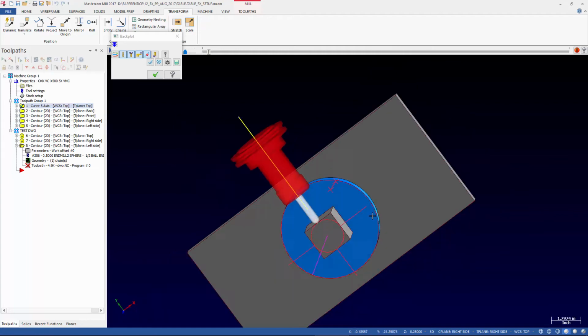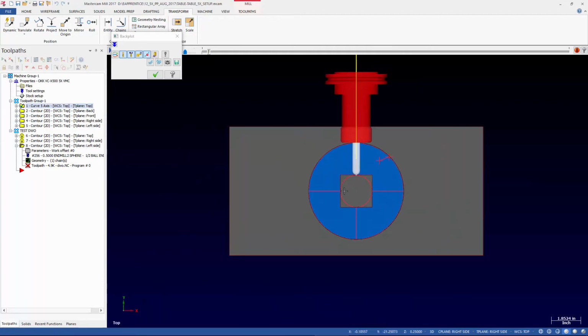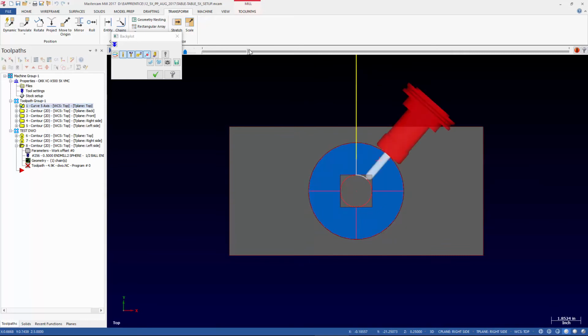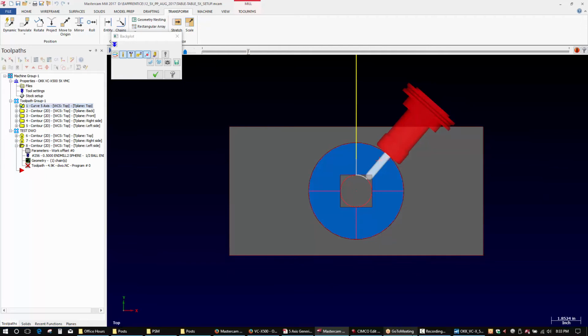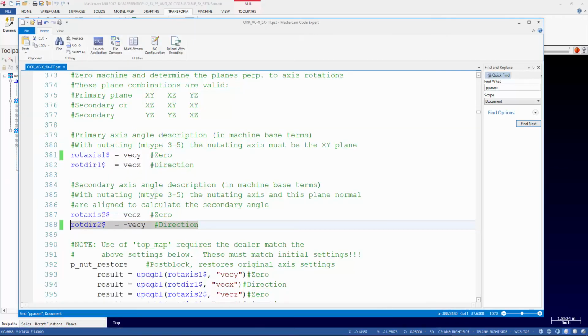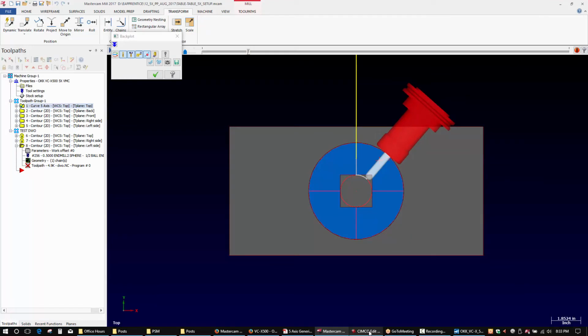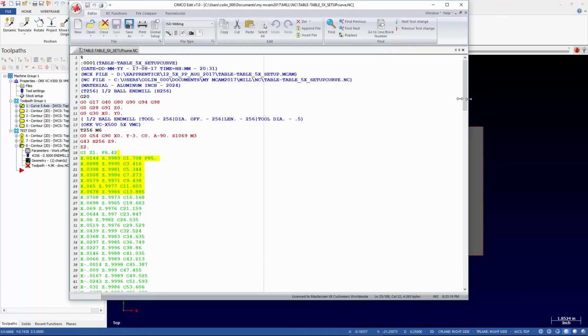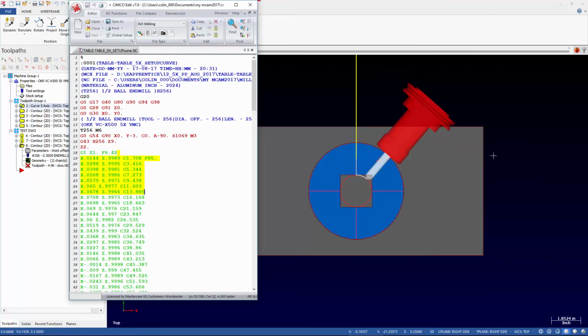If we look at it in top view, we're moving clockwise. Is clockwise rotation positive? That's the question. Because that's what we're getting in our NC code. Now, counterclockwise is the standard. That doesn't mean it's true on that machine.